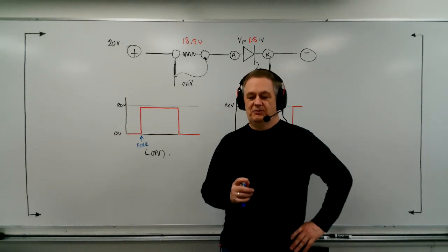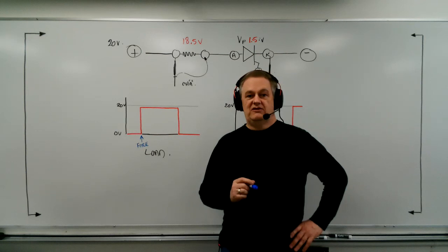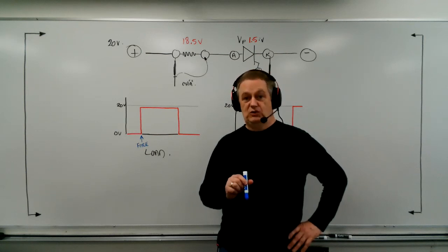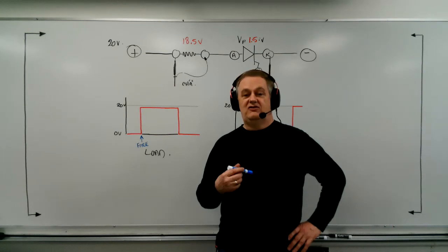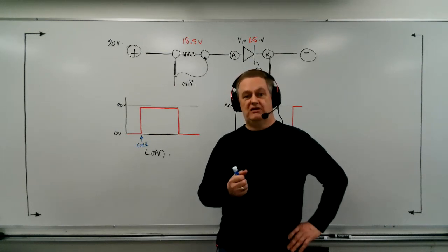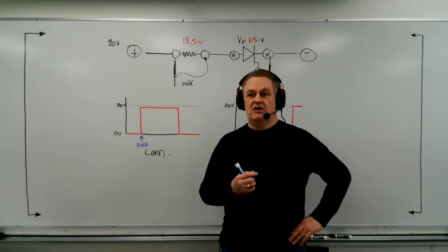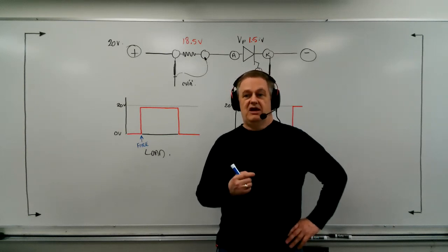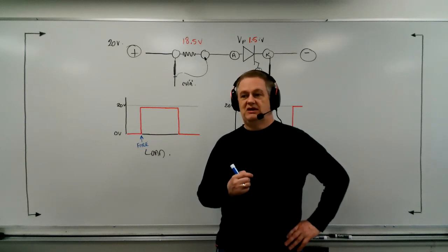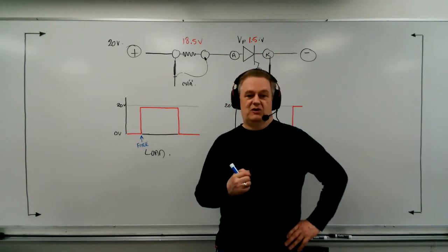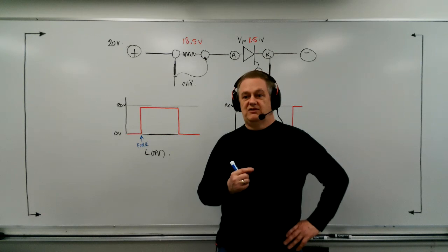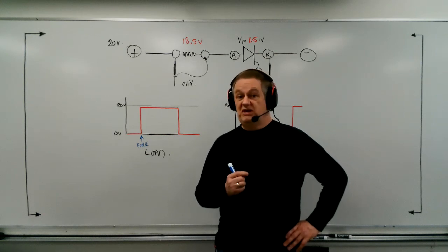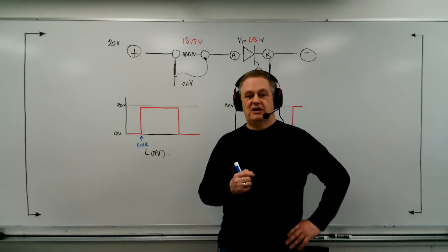So the next thing we're going to be doing is seeing how we can actually use this as the way that it's named, which is as a rectifier. We'll be taking this SCR and hooking it up in AC, and you go, wait a minute, it's a DC component. Yes, that's true, but it's going to be like a diode. It's going to give us a DC output, but it's going to be controllable, unlike a diode. And so we're going to now be able to take either the whole alternation or just a piece of the alternation. That's what's coming up next.